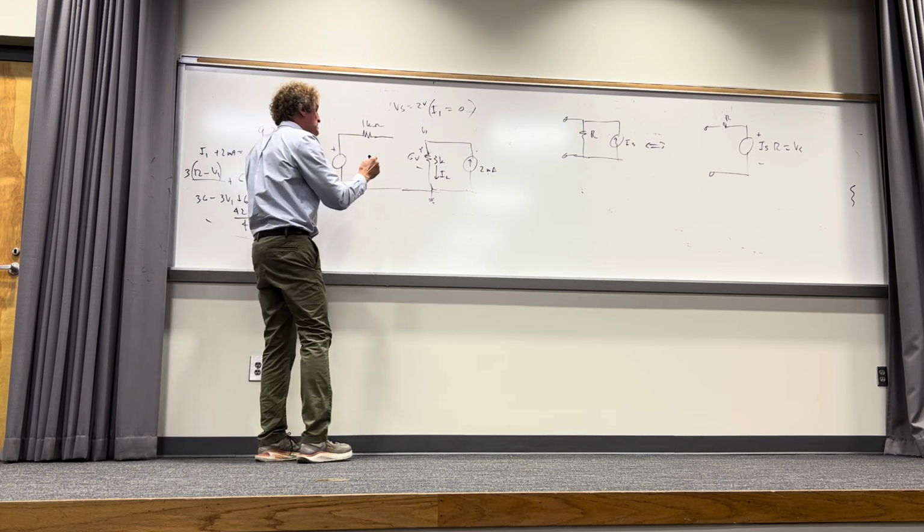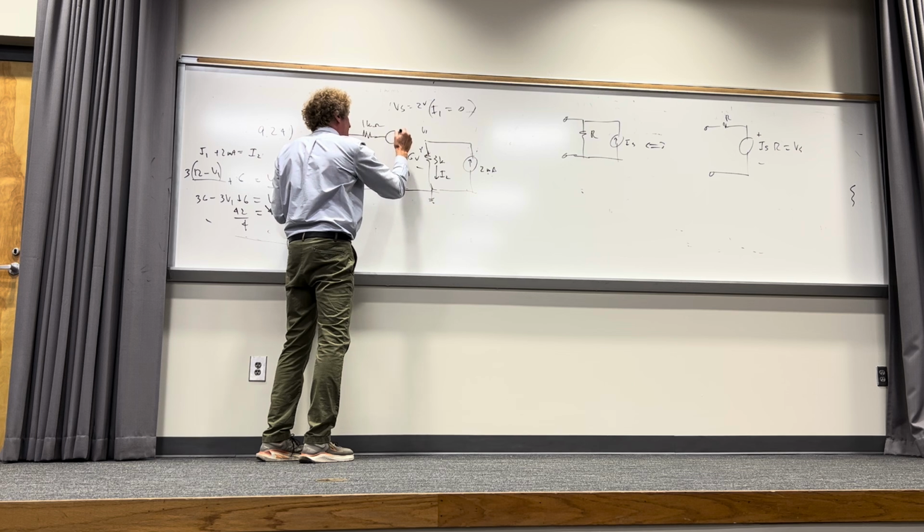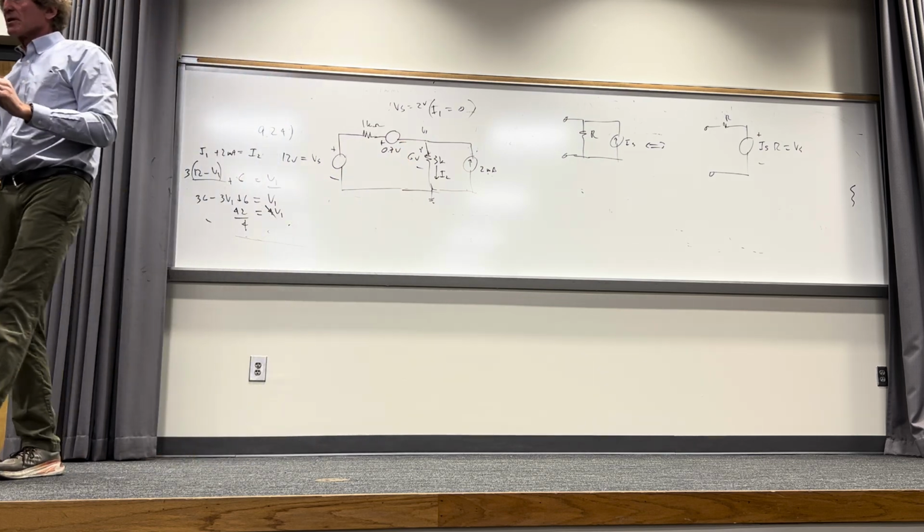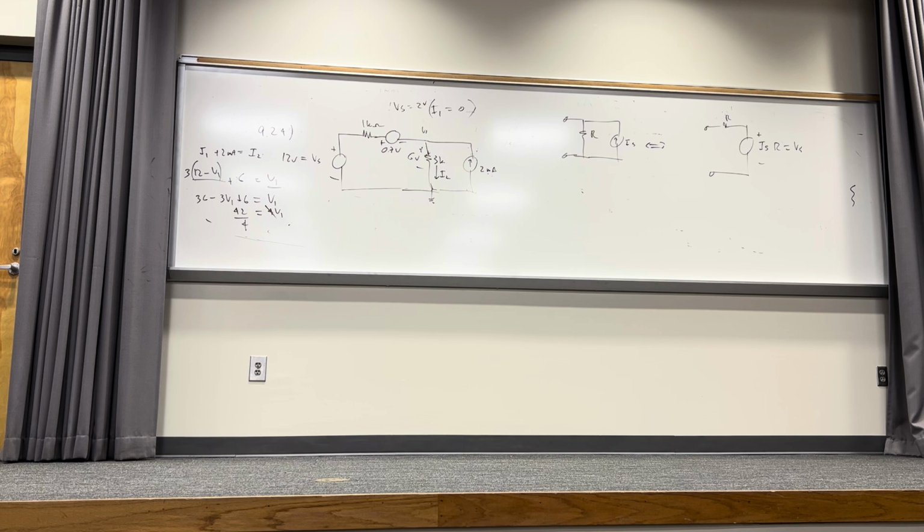But what you need to do is put a small voltage right here that would be plus to minus 0.7 volts if it's not ideal. You can replace the diode with a short circuit. How many understand it? Because it's on, right? Do we agree it's on? And then you can go about the analysis.